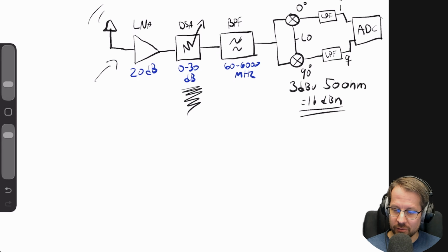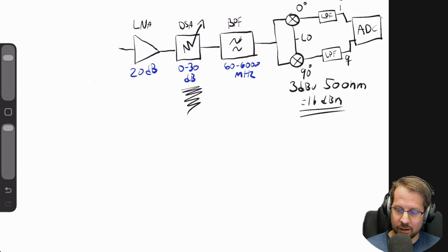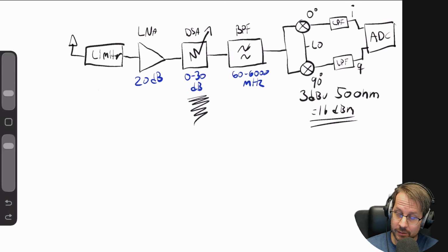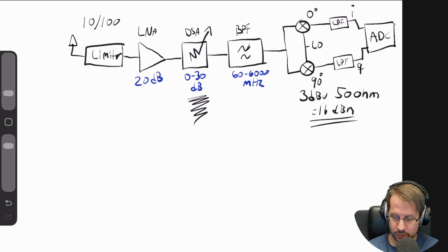Because there is one last thing here. There are the typical limiters, and the limiter helps by clamping down any strong signals so they will not enter and damage components at the damage level. So a typical RF limiter can be from, let's say, 10 watts to 100 watts.